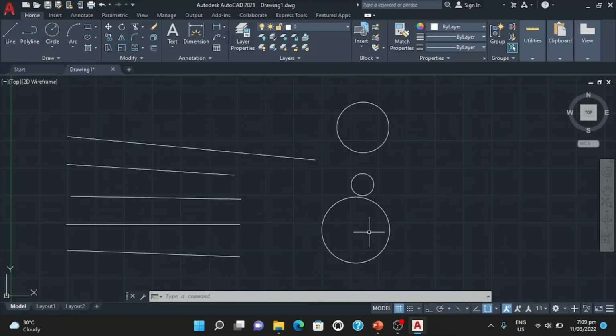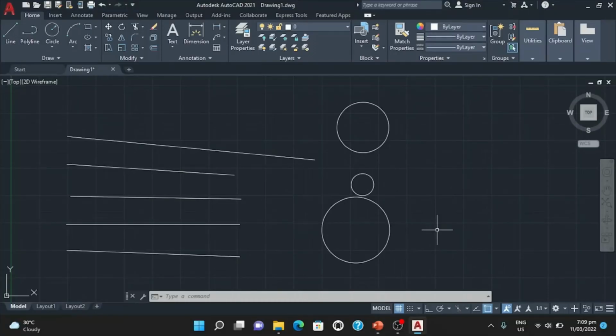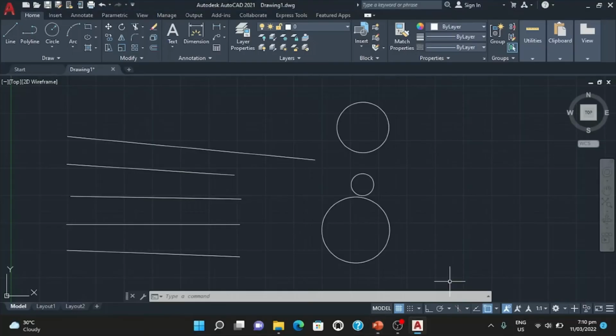Now, what if I want to create a circle using a diameter? In circle, the default is radius, R or absolute, where we just type the value of our radius. If we want a diameter, we press C for circle, then click a certain area of this part.